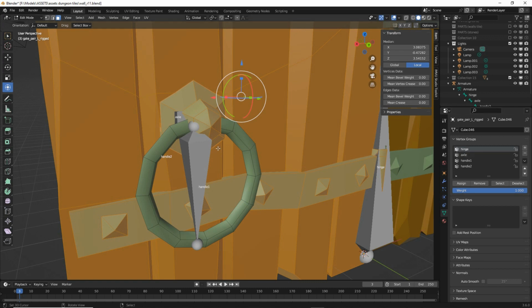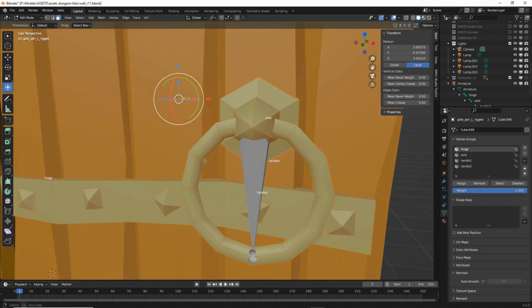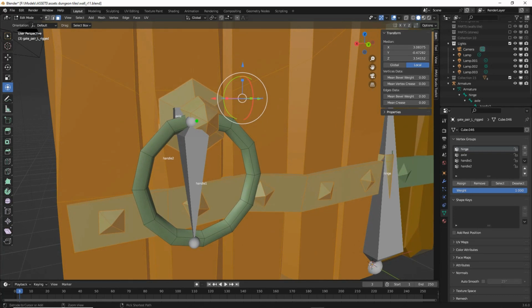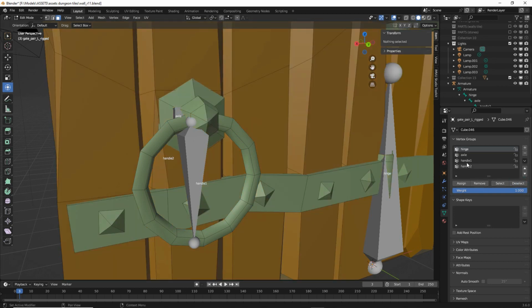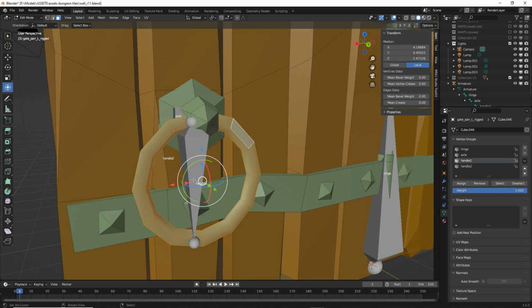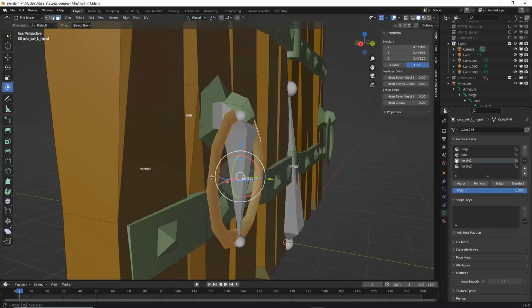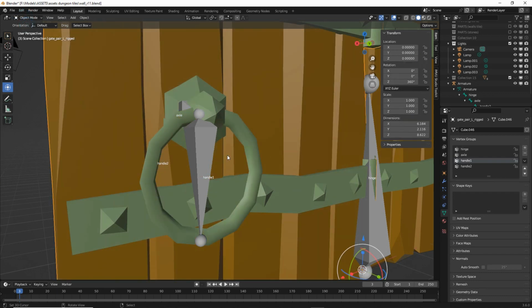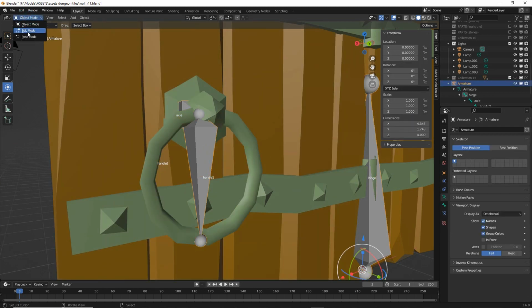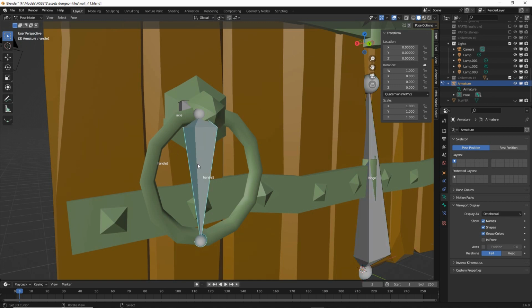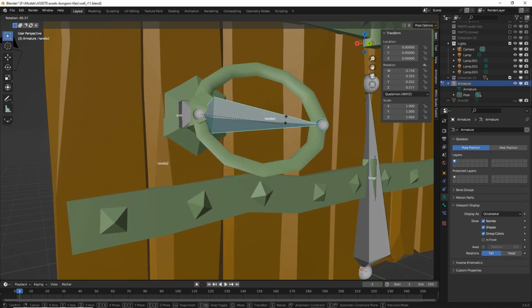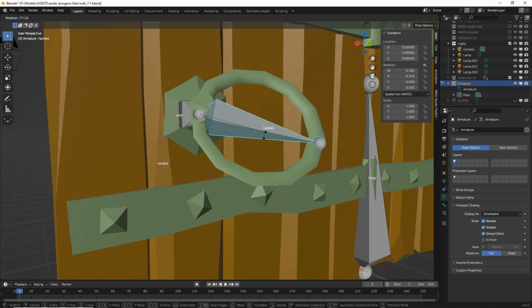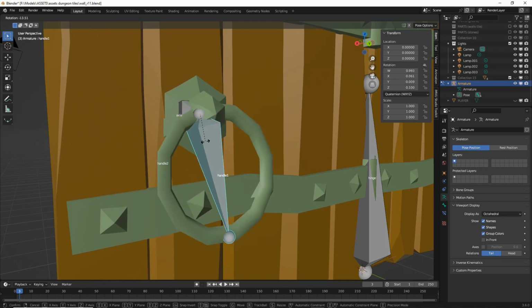So we can do that on both sides, but we'll deal with this for the moment because we need to check now. So deselect, handle 1, select, and that should only select handle 1, and it does. So we can drop out of edit mode into object mode, select the armature, object mode, pose mode, select the bone, press the R key, and that rotates that section of the mesh only.